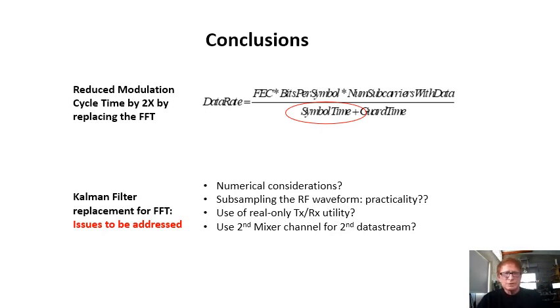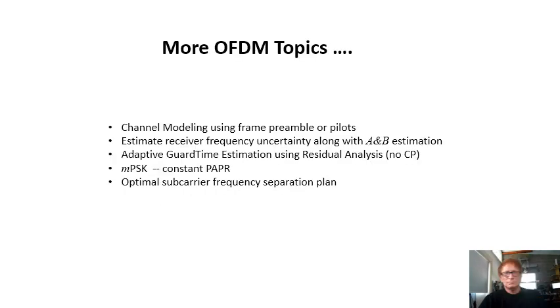We have also discussed multi-carrier mechanizations that use only a real output from the transmitter rather than the real and imaginary time histories as with OFDM. For such a real information signal, can we use OFDM's IQ mixer for a second completely independent information signal, which would in fact be another way of achieving a 2x data rate? The proposed data rate improvement alone is sufficient to warrant further investigation of this method.